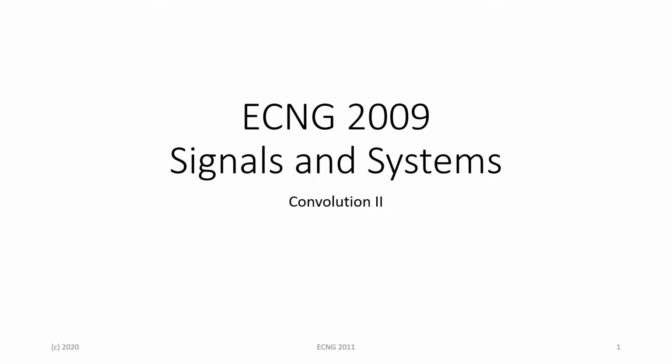Now, for this particular lecture, Convolution 2, in the last lecture that we did yesterday, we saw that for Convolution 1, we basically formulated the convolution integral from the convolution sum equation. And the convolution integral is actually what's going to be playing a very important role as to how we evaluate convolutions in the time domain. And that forms the basis of what we're going to be doing in this lecture, Convolution 2 here today.